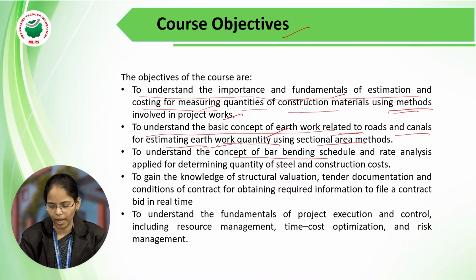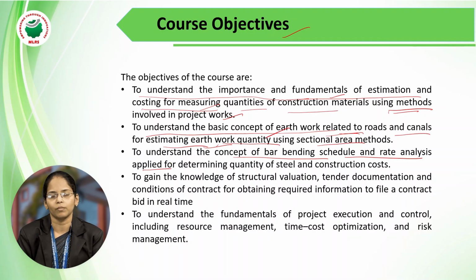And next, the concept of bar bending schedule and rate analysis. In this subject, we learn bar bending schedule. For any project, suppose we are constructing a structure, we need to design slabs, columns, beams, etc., which are reinforced. Reinforced means we need to give bars, with sizes like 8, 10 mm, etc. For a slab, we use 10 mm bars. If we take columns or beams, 12 mm, 16 mm, etc., depending on the structure strength. For what purpose we use the structure, we design the size of the bars.